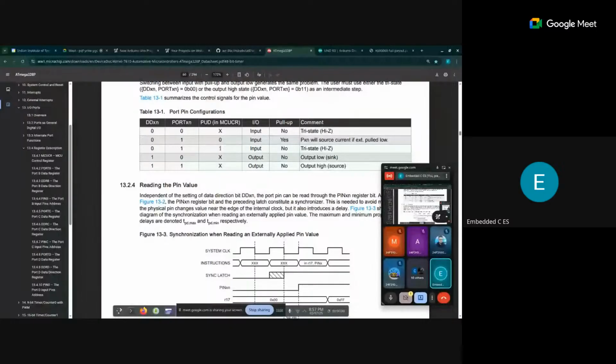If we enable this, there will be no pull-up. So we are going to disable this. We'll set the data direction to 0, and we'll set the port value to 1. Just the port value sets the voltage to high, so basically turning it to pull-up mode, right? This is what we want. So we'll be setting this to 0 and this to 1 for that.